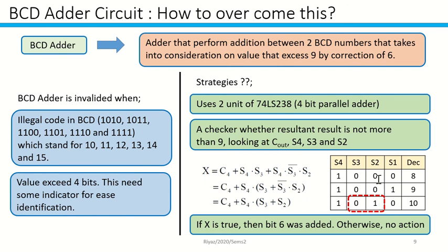So we want to check. For the decimal, number 8 is 1000, decimal 9 is 1001, and decimal 10 is 1010, as mentioned earlier. Before 8, it is going to be 0111, which is number 7. So whenever S4 becomes 1, this is activated, but S3, S2 and S1 are 0. For the number 9, S1 becomes 1, but since it goes 0, 1, and 0 again, S1 cannot be used as a result. The thing that is uniform is S3 is 0, S2 is 0, and suddenly for the decimal 10, S2 becomes 1.